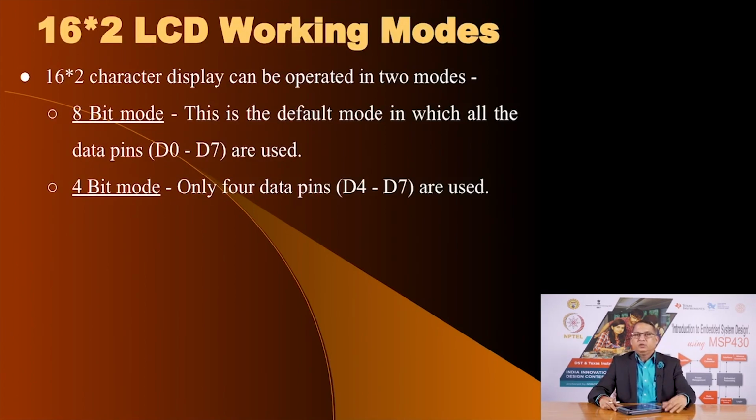I will come to that in a brief moment, but let us go back to the interface of the LCD. Now, because you have 8 pins for interaction, the controller inside the LCD expects you to send commands over these 8 pins, but oftentimes we do not have 8 pins. The Hitachi interface is very benevolent in that sense, in that it will adjust to sending information on 4 bits also. Instead of 8 bits you can communicate with the LCD controller on 4 of the 8 pins, and that is called the 4-bit mode. The default mode is 8-bit mode, but if you do not have pins you can select the 4-bit mode.